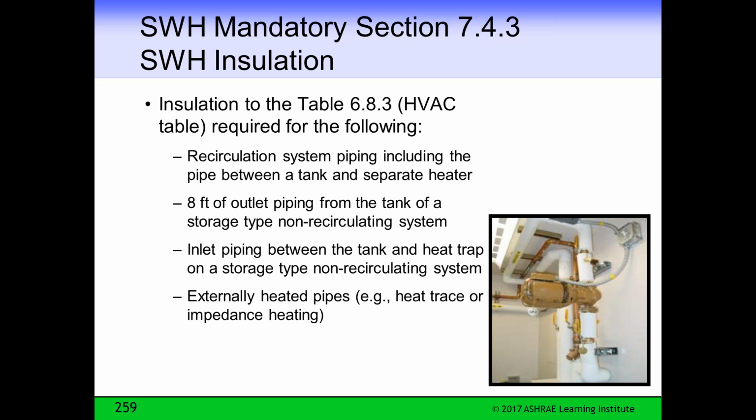So the part that is not part of the recirculating system, the deadhead piping that leaves the recirculating system and runs to the fixture, is not required to be insulated. Now, for good design, how long should we allow that to be? And that's being debated now.